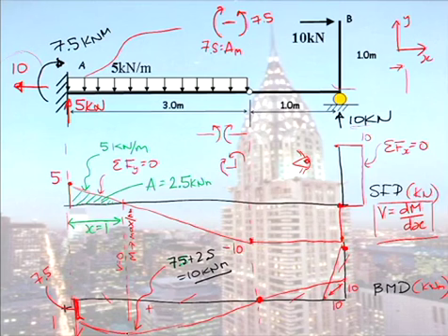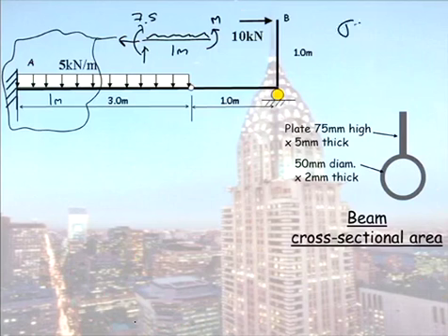Okay, we have our bending moment. Why do we need our bending moment? Because our bending stress, maximum stress occurs where our M y is maximum. So our maximum moment will either occur here in the corner where it's 10 or down here where it's 10. So far so good? Okay, so looking at our formula, we still have to calculate our moment of inertia, our second moment of area. And we will do that now quickly.